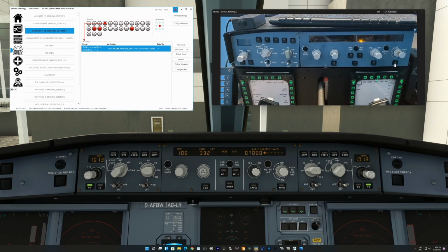The last one is basically vertical speed. Here the dash means it's managed, but if I push this one once, it will be in selected speed mode. Okay, so here I'm in the selected mode, so 00. I push once here, so you can see it's number 16, so it's on and off. Push pull event. That is something that I'm using this one to select, or if you push again, I think it's becoming level, right?